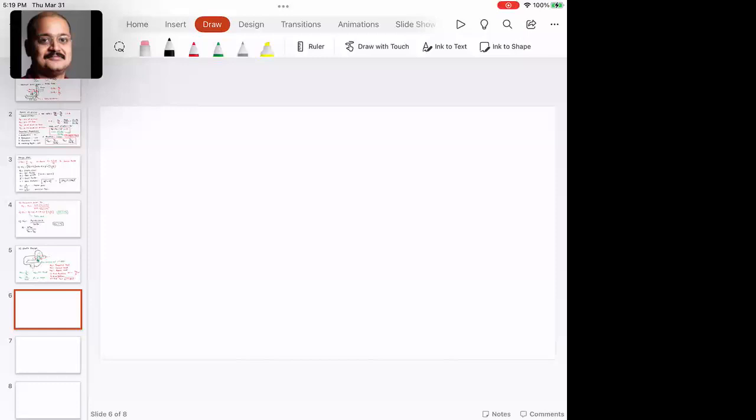So let me ask you this question, just from practical experience. How do you know that a gear train is efficient or inefficient? If you see a gear train, it would be in a gearbox, right? If I ask you, these are two gear trains, this is one gearbox, another gearbox, can you tell me which one is efficient? What would you do? The first thing you should do is touch it.